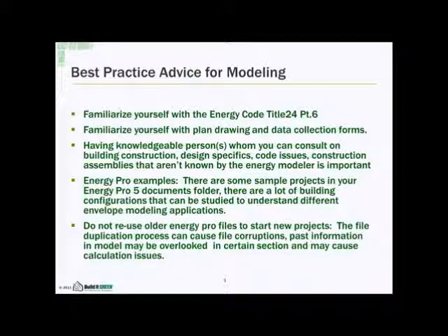You should understand how to read plans, drawings, and data collection forms, which vary between businesses. So have a good relationship with the person who gives you the data collection form, or if you're the one collecting the data, make sure you understand how to fill out the forms, so that when you get back to the office you can read your forms and not get confused by your own data collection.